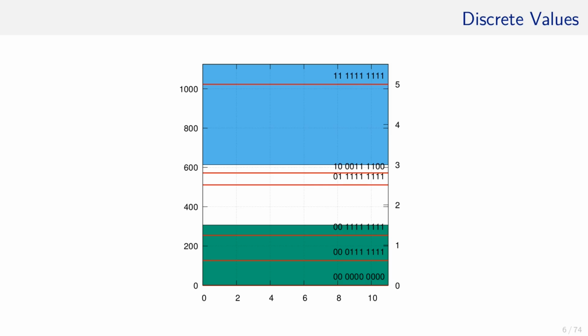Unfortunately, there is no infinite accuracy in the digital domain. So currently we have to be happy with 1024 values, which can be represented using 10 bits and a maximum error of around 4.88 millivolt.